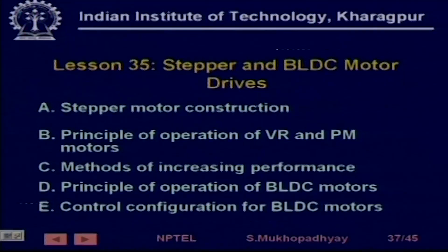Then we took a look at two kinds of motor drives. One is stepper motors, which have very simple and cheap drive electronics, and are used for non-critical applications and for smaller applications having smaller power ratings. And then we also took a more detailed look at BLDC drives, which are becoming very popular, basically because of the improvements in magnet technology.